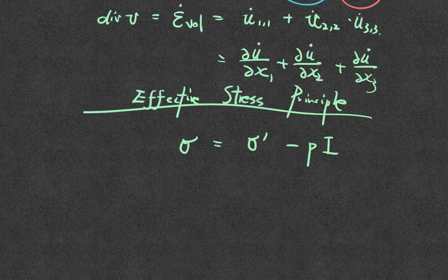Here we're deriving that in a more mathematical sense, in the sense that positive is in the tensile direction. In conventional soil mechanics, compressive is given as the positive direction, just for convenience. But here we are trying to derive the boundary value problem, so it's more convenient to consider the tensile part, the thing that expands, as positive, to be consistent with the mathematical behavior.